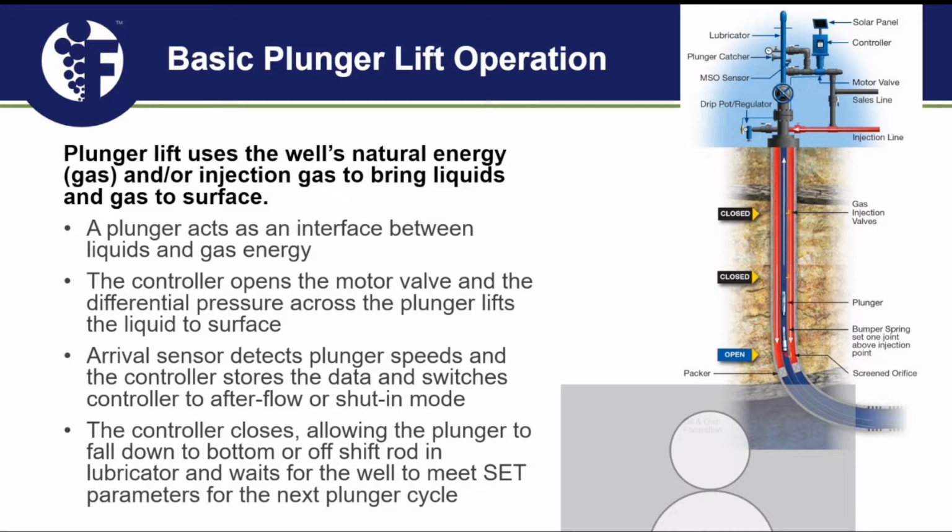Mm-hmm. The energy provided from the gas, either formation gas or injection gas or a combination of both, depending on what we're looking at from a plunger lift standpoint. Yep, good point. And up at surface, included with the lubricator, is typically some kind of electronic controller. This is going to register when the plunger arrives and dictate the cycles. One interesting thing, and I know you've seen it from your past experience, is the improvements or changes of this controller, right?